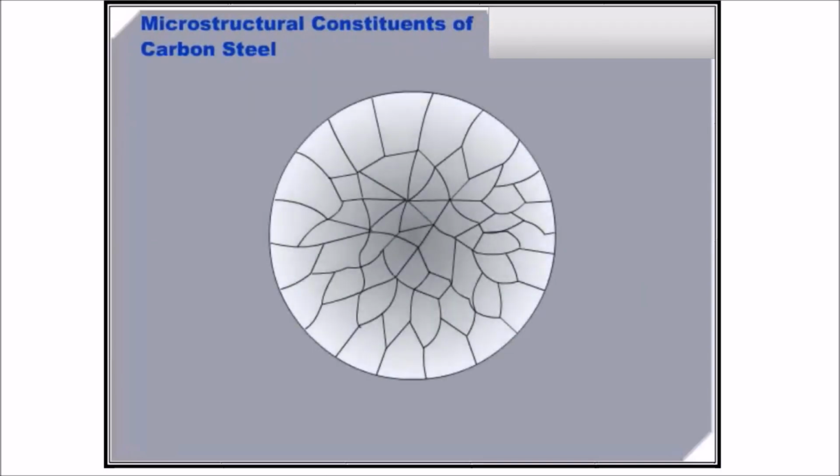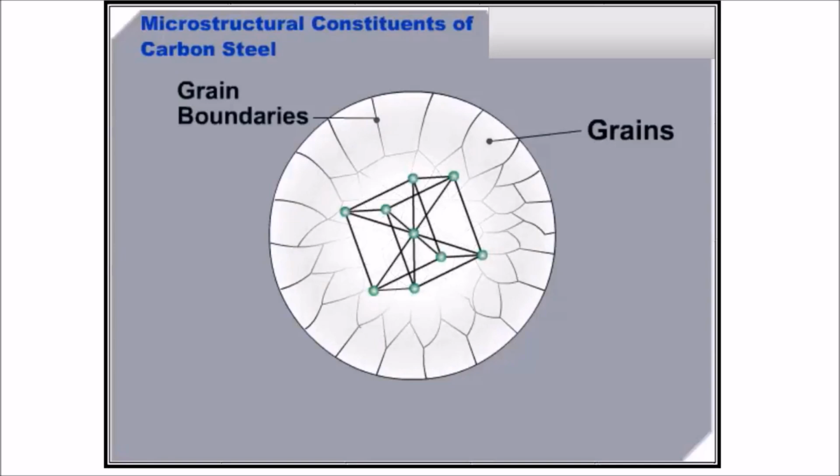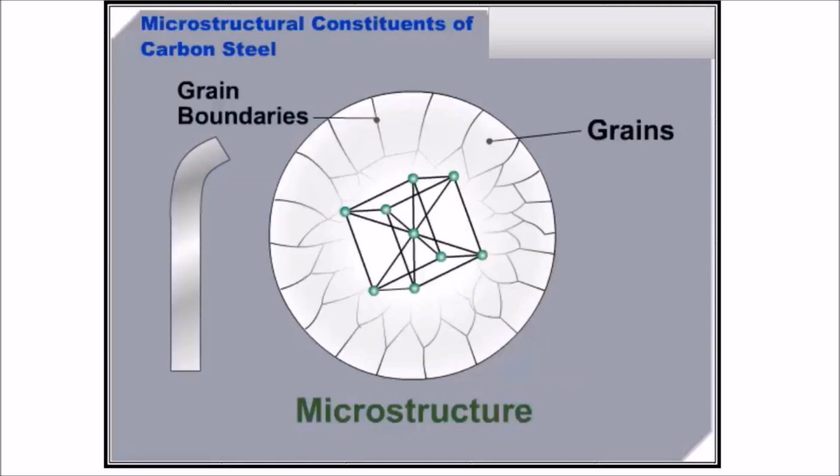The overall arrangement of grains, grain boundaries, and phases present in a metallic alloy is called its microstructure. The microstructure is primarily responsible for the properties of the alloy. This microstructure is affected by the composition or alloy content, and by other factors, such as forming and heat treating operations. The microstructure is greatly affected by the welding operation, which, in turn, influences the properties of the alloy.